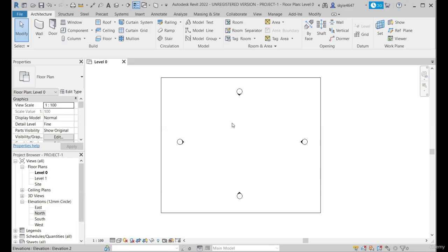floor, walls, etc. And we also need to be careful: whenever we associate any element to a particular level, if we modify or delete the associated level, the changes will be incorporated into the hosted models likewise. And grids are annotation elements that help us organize our design.